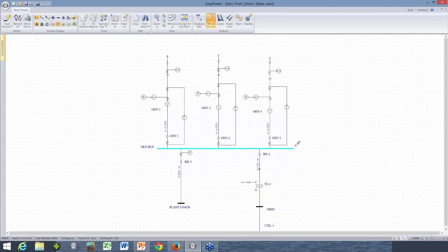So I get a total fault current of 400 amps. That's basically 100 amps from each one of these sources through its 100 amp resistor. And I can see that if I switch, instead of looking at A phase current, to the 3I0, I'm going to see 100 amps ground current from each source. Okay, so that looks reasonable.